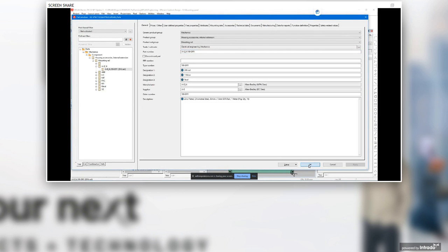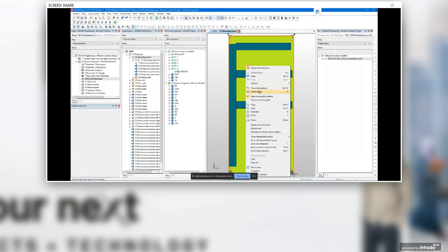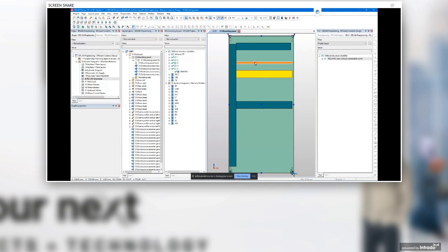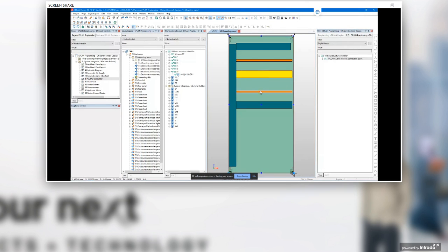So now I can say I'd like this DIN rail to be the same size as this DIN rail here. And I want to place it centered between these 2 DIN rails. So it automatically now centers it and adopts the length of that particular wire duct. So it's easy to lay out your components. Again, here I can move this if I wanted to a bit closer.